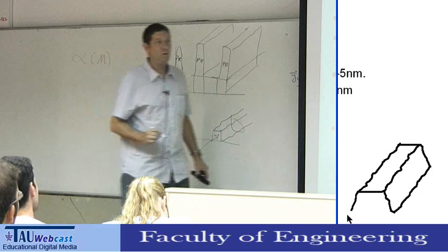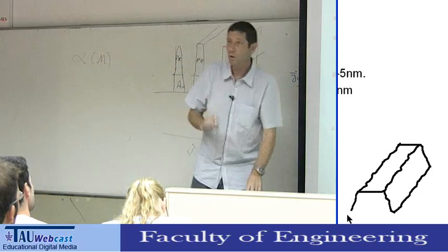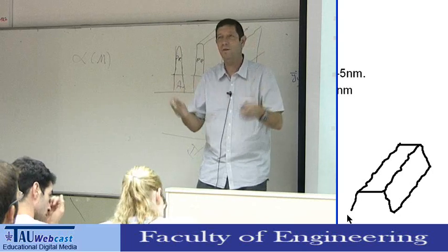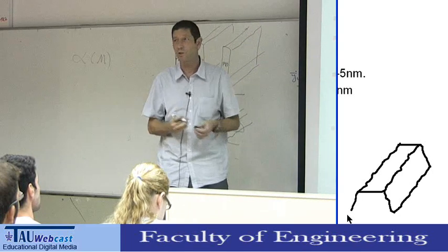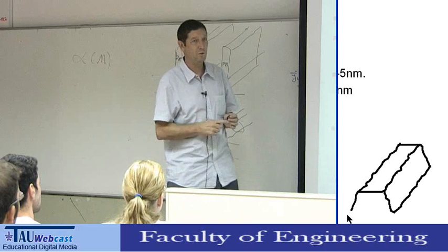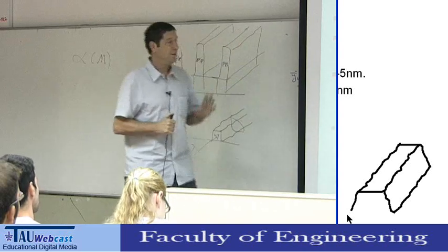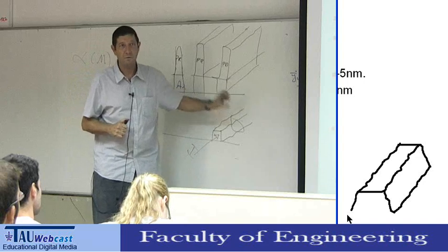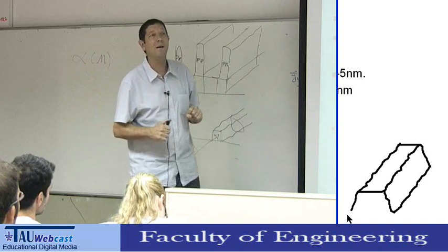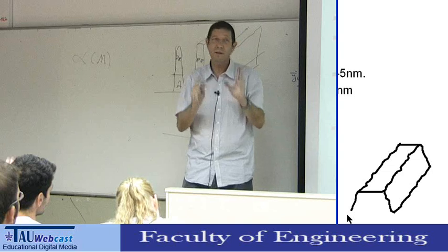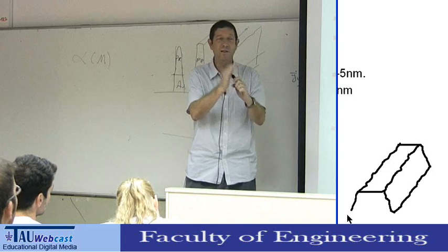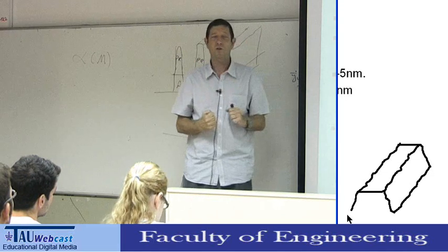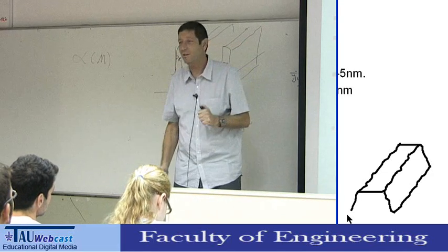And there's a very strong correlation between the quality of the lithography and the reliability of the lines. I will not go into detail. This is something which has been investigated in the last few years. It's not fully understood. But there's a very strong correlation between the quality of lithography and the reliability of the lines. You can think about it. If the line is very smooth, there are fewer defects. If it's not so smooth, you can have corners and some structures, but this is material for another class.